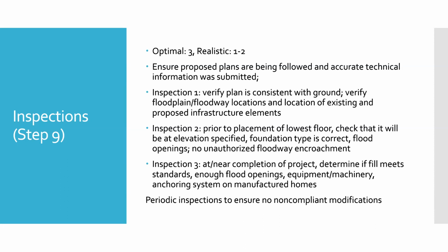And inspection 3 is at or near completion of the project. So you want to make sure that the fill meets the standards, that there's enough flood openings, they haven't covered the flood openings, that the equipment and machinery is properly elevated. That's really important. Anchoring systems on manufactured homes, that kind of thing. So after this, you'll want to come back and conduct periodic inspections to ensure that no non-compliant modifications have been made.